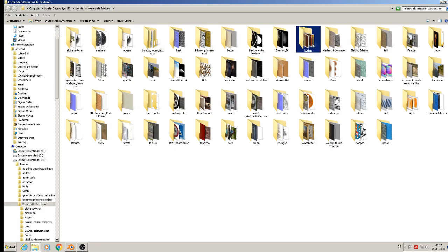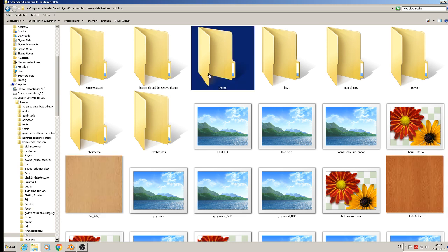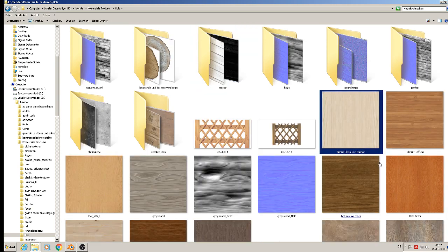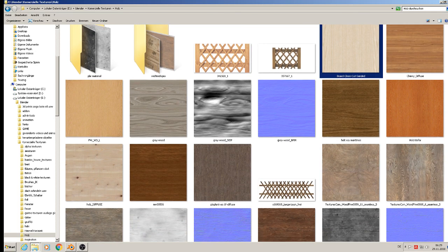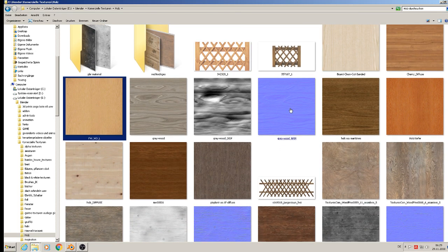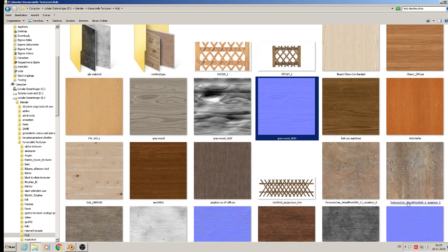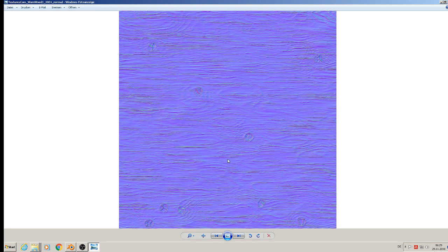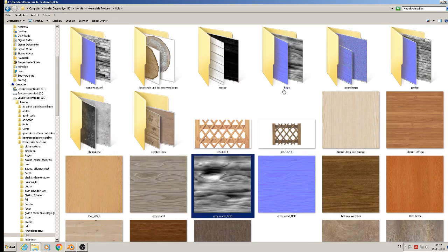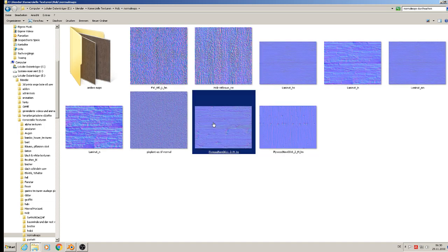You can get wood materials from textures.com, and then you use the program GIMP, like Photoshop, and there is an add-on that is called Insane, and there you can make from a texture a normal map. That you have to do. I have done that before, so I simply take the normal texture that looks like wood and place them there. I must only find the right one that looks interesting.